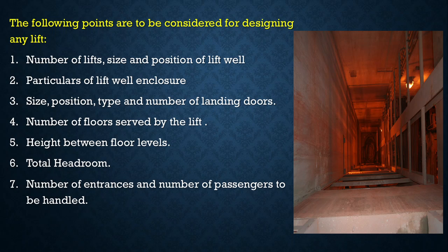Size, position, type, and number of landing doors. So how many doors, landing doors. So in different levels of your floorings, you will have different doors. So how you are going to position it? What type you are going to use? Number of landing doors, size. So you have to consider it.